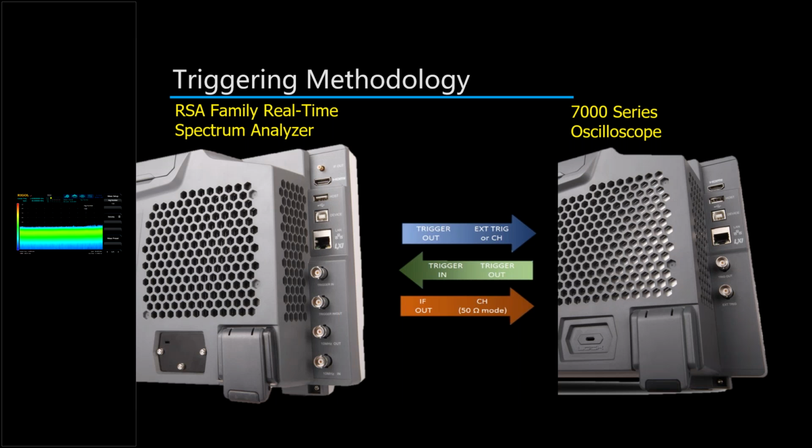down at 430 megahertz. We've also created a double-ended triggering here. The triggering on these two instruments is so flexible that we're able to set a trigger out line from the spectrum analyzer to the external input trigger on the scope, and we have a trigger out function on the scope that's able to go into the trigger input on the spectrum analyzer. So we'll use both of those as we try to solve different types of problems that we think require a different approach.